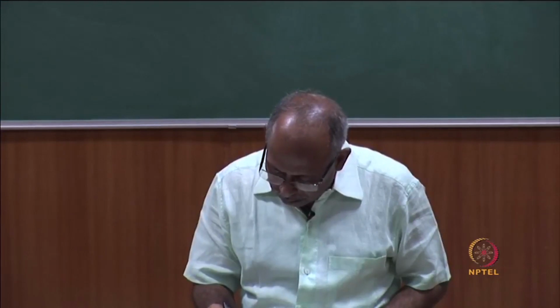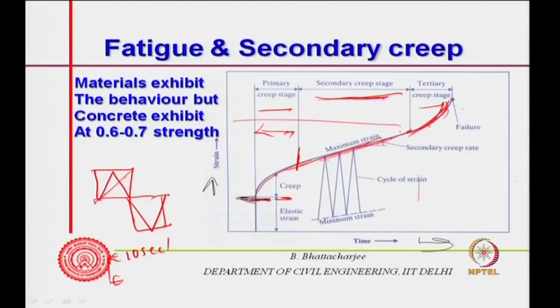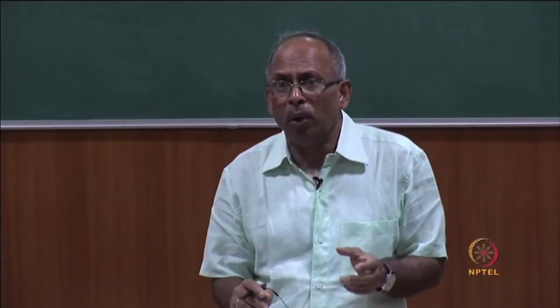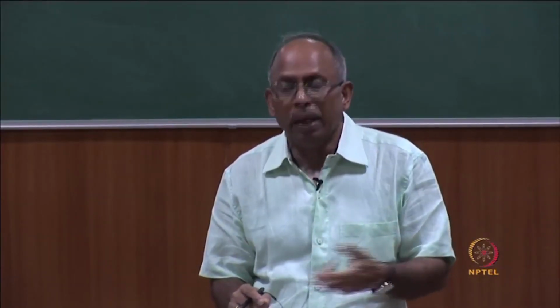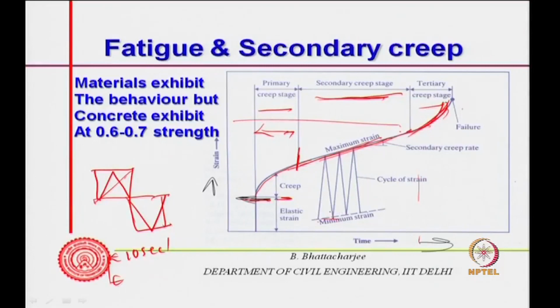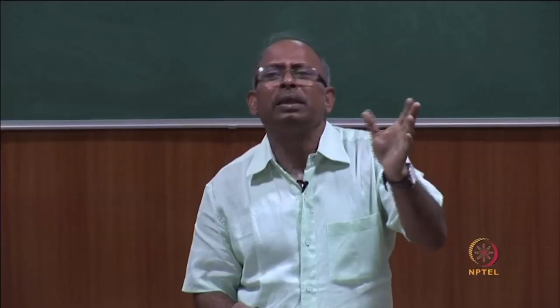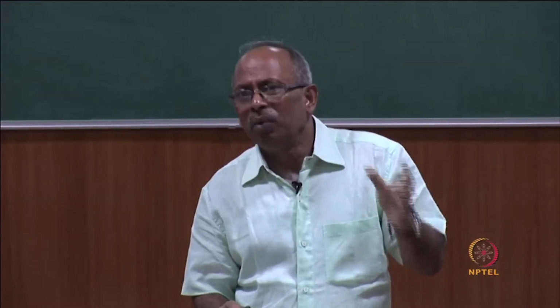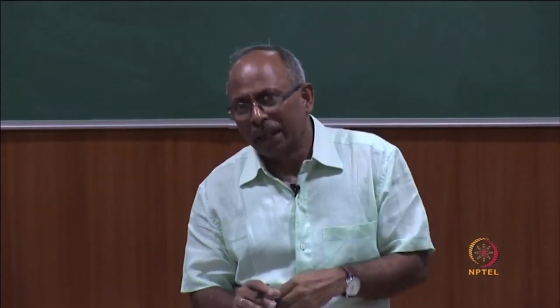So, when I have reversal of stresses, it goes to a minimum, but then the load is still sustained, it is not gone away. So, when I come back, I do not come back to this point again, but I come back somewhere above, because load has been sustained for a certain period of time. In the second cycle, the cycle time is small, the time period is small. So, 1 over time period, frequency is very high. Extremely low frequency, 0 frequency, is sustained loading, high frequency is a kind of fatigue.